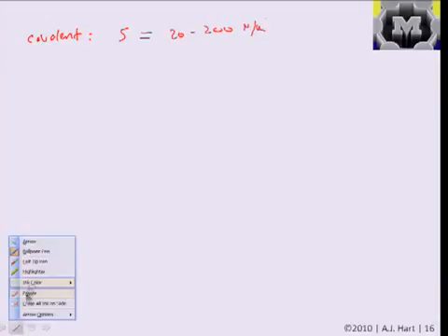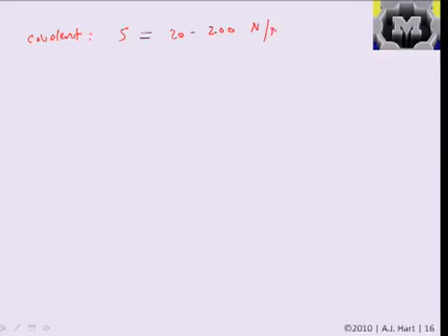So if we use this approximation to think about the Young's modulus of some materials, what we want to do is look at the interatomic potentials for different materials or different types of bonds. As a generalization, it may be found that covalent bonds are the stiffest and have the strongest interaction, because you actually have electron transfer, mating of the outer shells from atom to atom. They have a stiffness S, which we'll say covers a generic range of 20 to 200 newtons per meter. That means you need to apply like 200 newtons to stretch an individual bond 1 meter. Wouldn't actually stretch that far, but as a picture.